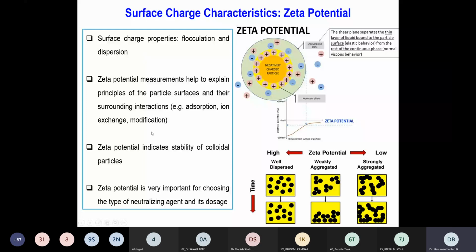Here you can understand the meaning of flocculation and the meaning of dispersion. When you add any additive, for example in the stabilization of expansive soil, they work basically on aggregation, that is flocculation, while some additives work based on dispersion. Or, if a chemical reaction has to happen homogeneously, the material has to be initially in a dispersed state, followed by aggregation or a flocculated state. Flocculation means the material becomes very hard. Dispersion means that every particle is in its individual state.